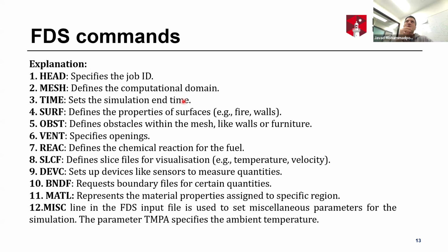So you need just to study the behavior of fire for example, 5 seconds, 50 seconds, 500 seconds. So it depends on your need. You can define the value of time yourself. Then the surface: you can define the properties of the surface. For example, I have a building, so I need to specify the walls or even the fire.